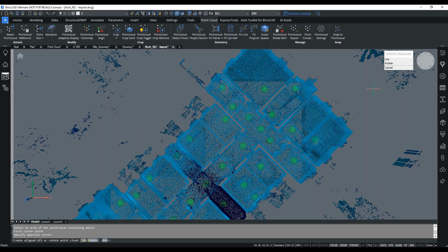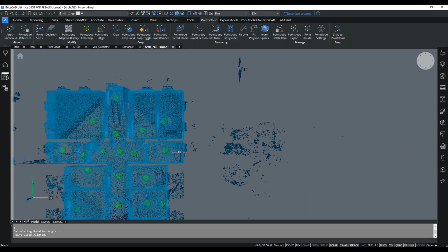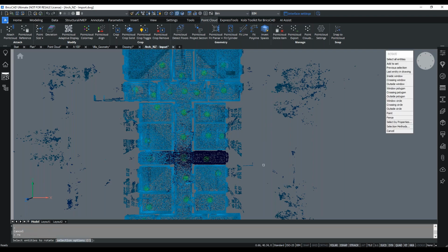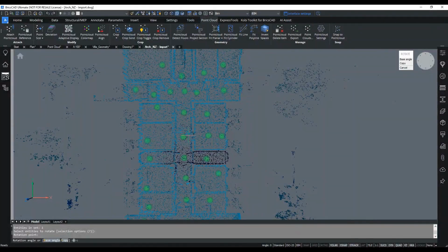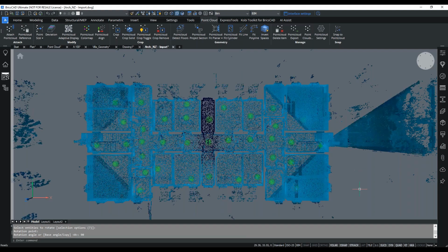When you do this, you get the option to rotate the geometry or do a UCS. I'll rotate, and if I did a UCS, I could have multiple versions. So if my building was more complex, where we had different orientations, I could have different scenarios for those areas. In this case, it's a very orthogonal XY orientated situation, so this works quite well. I will rotate this so it'll work horizontally across my sheet for my final plan view. And now we are ready to start working this out.